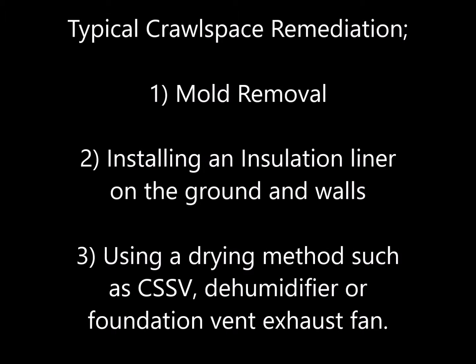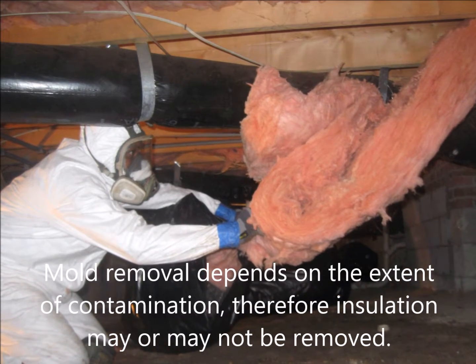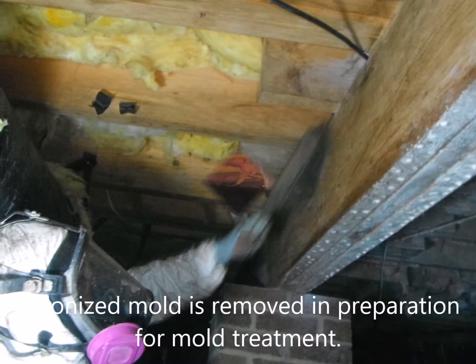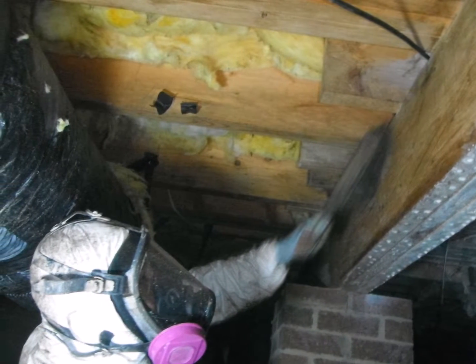The typical crawlspace remediation consists of mold removal, installing an insulation liner on the ground and walls, using a drying method such as a crawlspace supply vent, dehumidifier, or foundation vent exhaust fan. Mold removal depends on the extent of the contamination. Therefore, insulation may or may not be removed. Colonized mold is removed in preparation for a mold treatment.